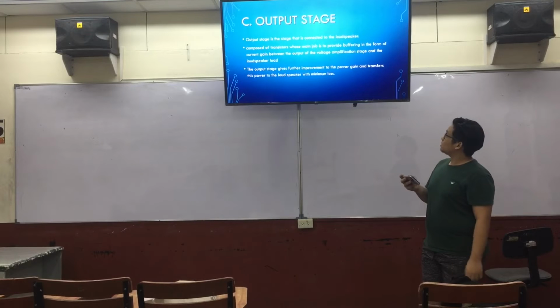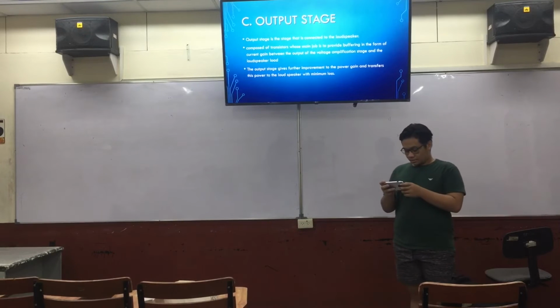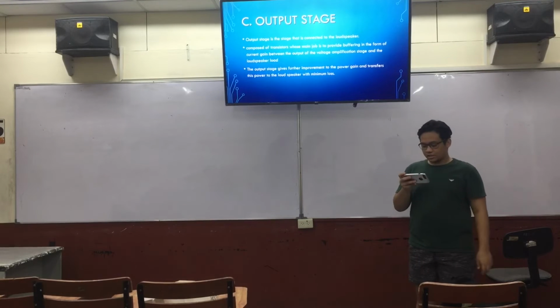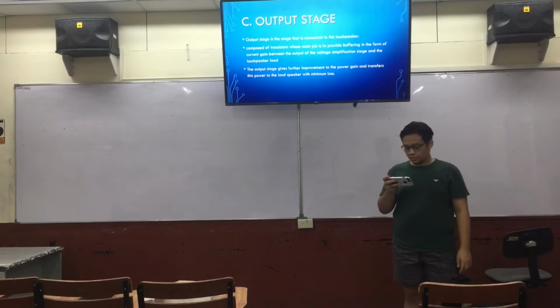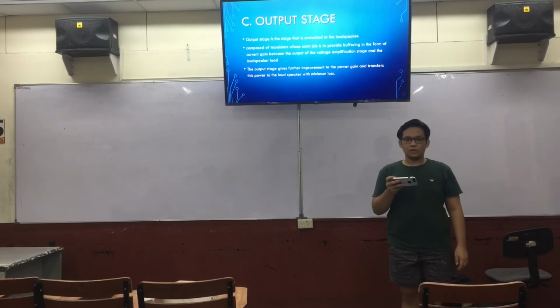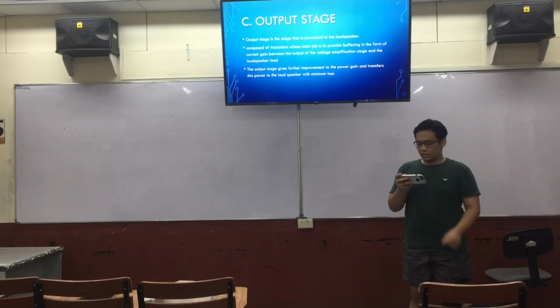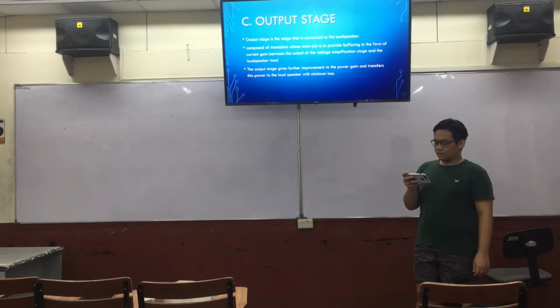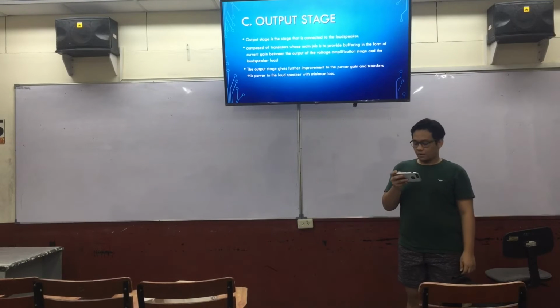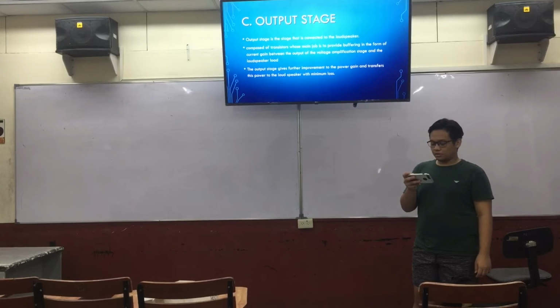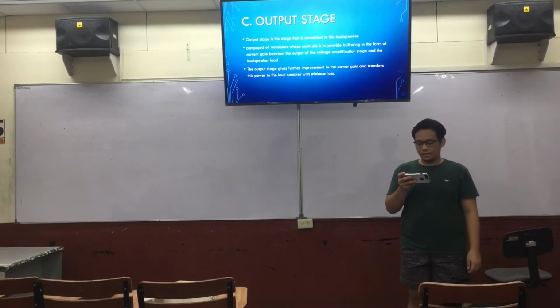Next is the output stage. The output stage is the stage that is connected to the loudspeaker. It is composed of transistors whose main job is to provide buffering in the form of current gain between the output of the voltage amplification stage and the loudspeaker node. The output stage gives further improvement to the power gain and transfers this power to the loudspeaker with minimal loss.